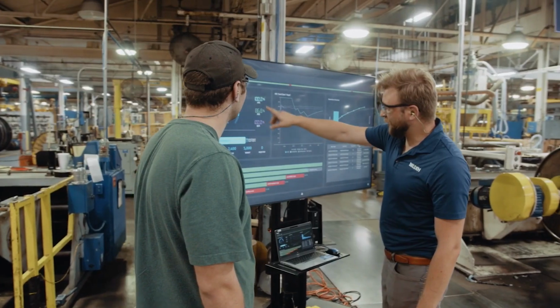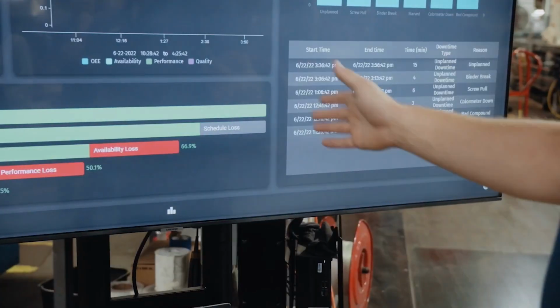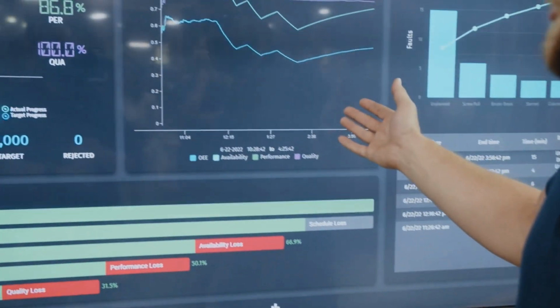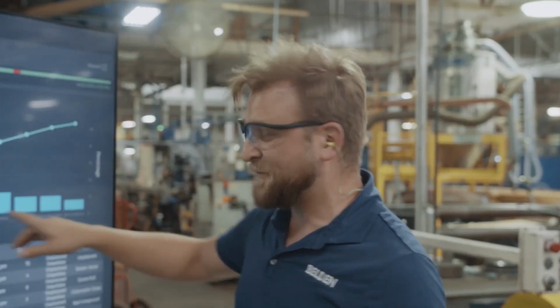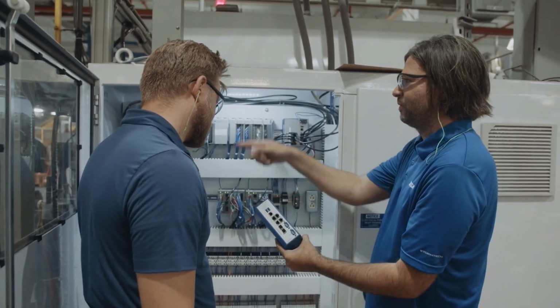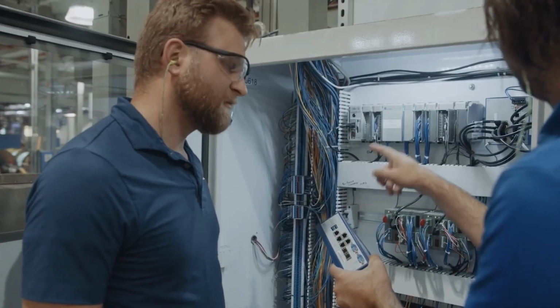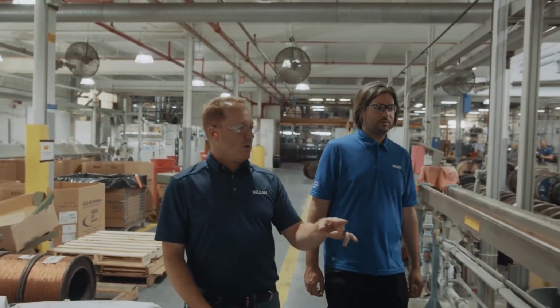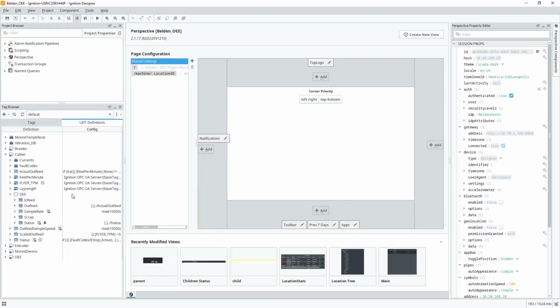This is possible by utilizing Ignition's wide array of drivers, of course, as it allows for easy connectivity to Allen Bradley PLCs and Modbus connections. We then used cross-database queries using SQL Server to pull data out of the database connections. Once this data was in Ignition, we could use Ignition's tag layer as well as SparkMES's UDTs to quickly pull the values in and get insights into the OEE data.